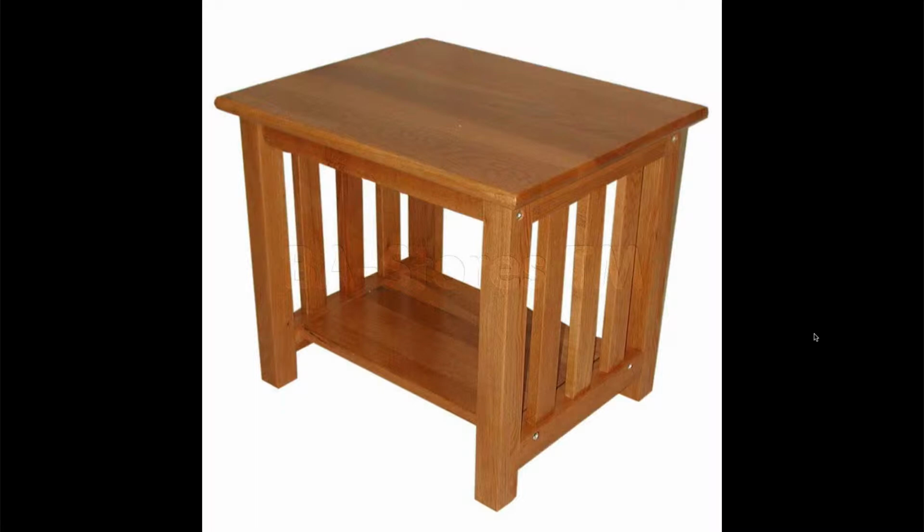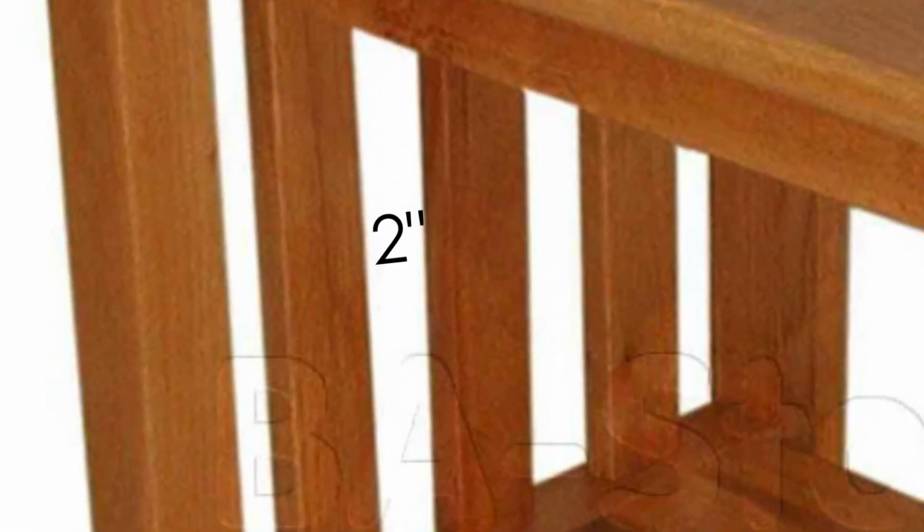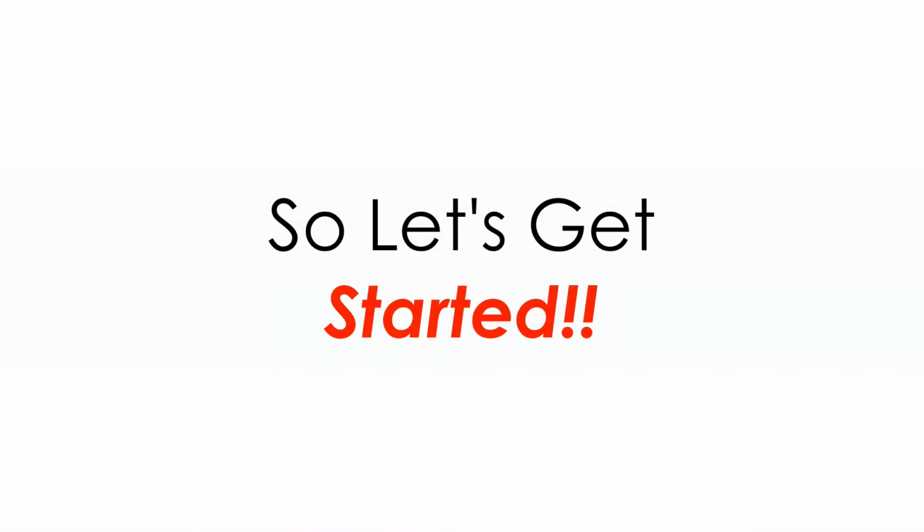I'm also looking to see that that front rail looks like it sits back just about 1/4 of an inch as well. And then I'm guessing that the legs are 2 inches by 2 inches. The bottom rail, I think, would be 2 inches by 2 inches as well. It looks to me like the side slats should be 2 inches wide by 3/4 inches thick, and about 2 inches spacing between. So why don't we go ahead and get started?